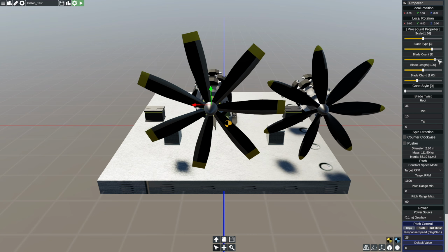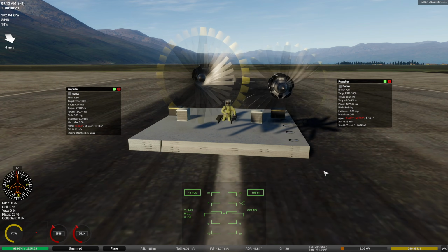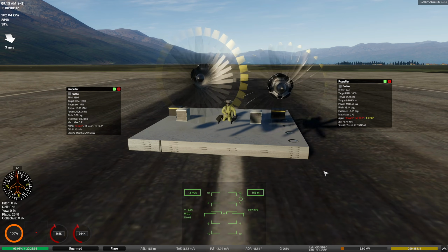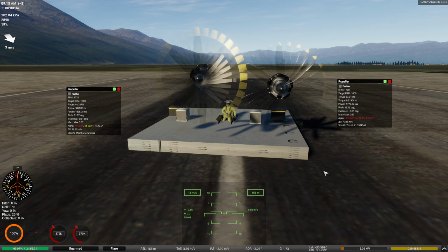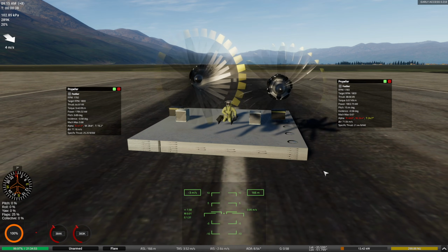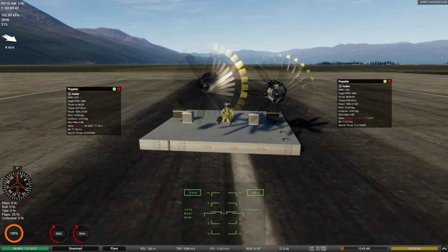The fifth and final type is tapered. Similar to the scimitar blade, the prop had to stall itself to meet the target RPM, and the only way it could get it to the target RPM was by changing gear ratio and increasing blade count, diameter, and chord. And while the end result was a more efficient prop, it was also significantly heavier than the control prop.